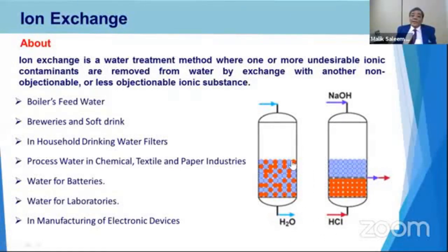We require at least 50 to 100% freeboard, so that we can expand our resin bed up to 50% or 70% as per the design requirement. When we fluidize the bed during the backwash, this media will expand and go up to the top. If we don't have the freeboard, this media will go out into the drain. That's the reply to your question, my dear.